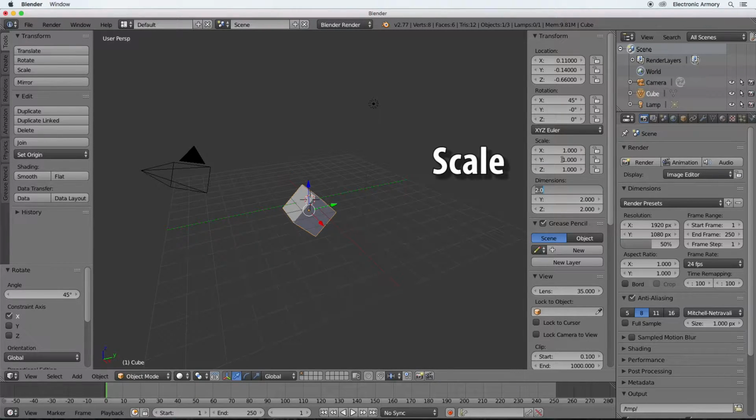That's okay. A best practice is to move your model in object mode and scale and rotate and do other transformations in edit mode. This retains the local geometry of the object as you would expect it. Let me show you the preferred way of scaling your object now. But first I'm going to set the rotation back to 0.